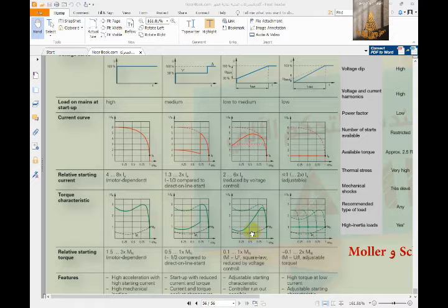And when you say soft starter, it's also starting with a very low torque. It's certainly starting from 30% of the voltage, so the torque is very low then, and it changes, and at last at this point reaches the full torque curve, and it's very good. But according to torque, still star delta is the joker here.